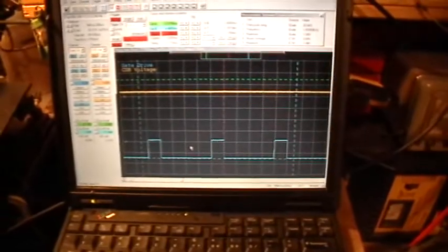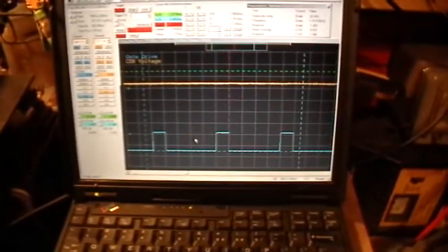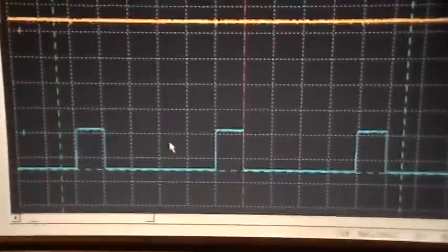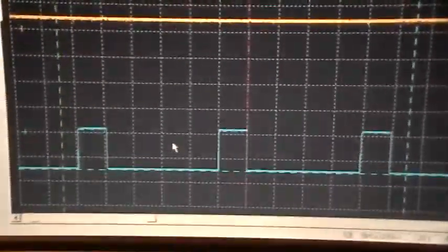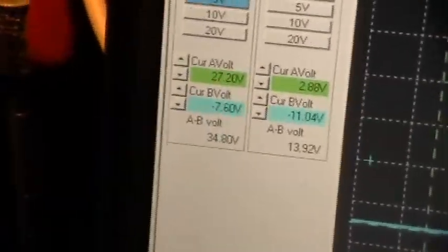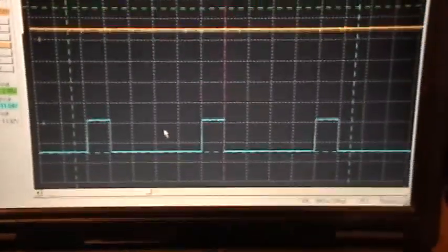Now we know the plus and minus settings on the function generator that caused the oscillation settings that we saw previously. And that took what? Under 4 minutes for the whole thing, and it's unambiguous. And now when I want to reset the function generator to produce those same oscillations, all I have to do is set it like this. 1 volt positive and minus 7.60 volts negative. Right? Thank you for watching.